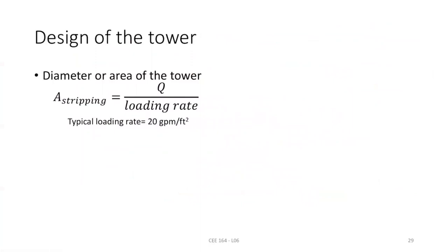Now, the question is, what's the design? What's the diameter it should be? As I said, you know the Q. If you know the flow rate, the water that you are adding, divided by the loading rate, you should get the area.